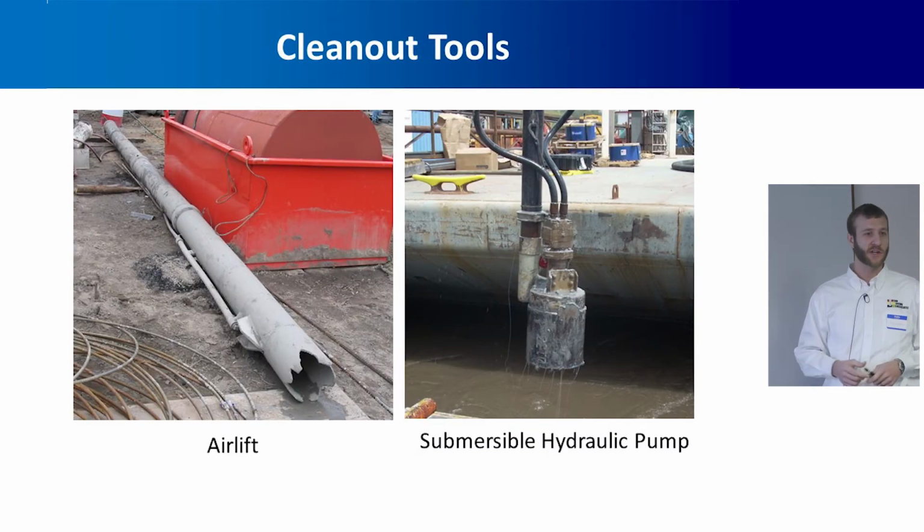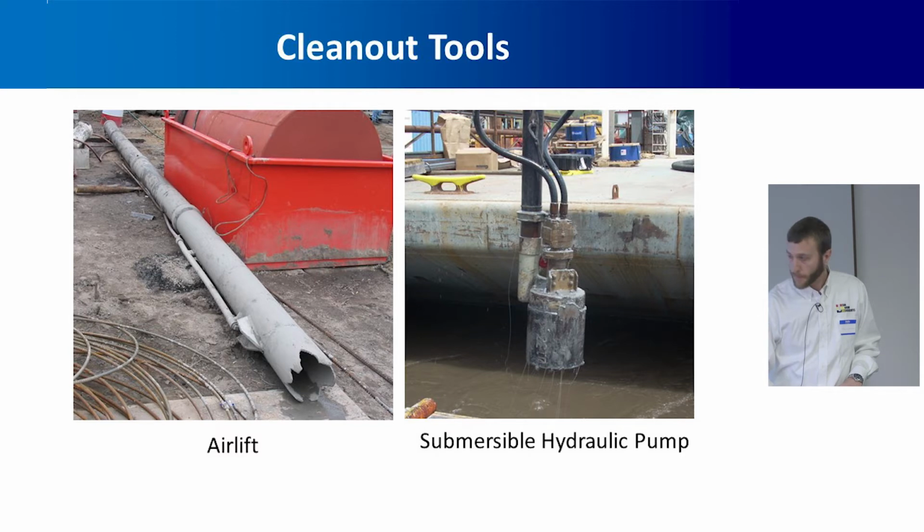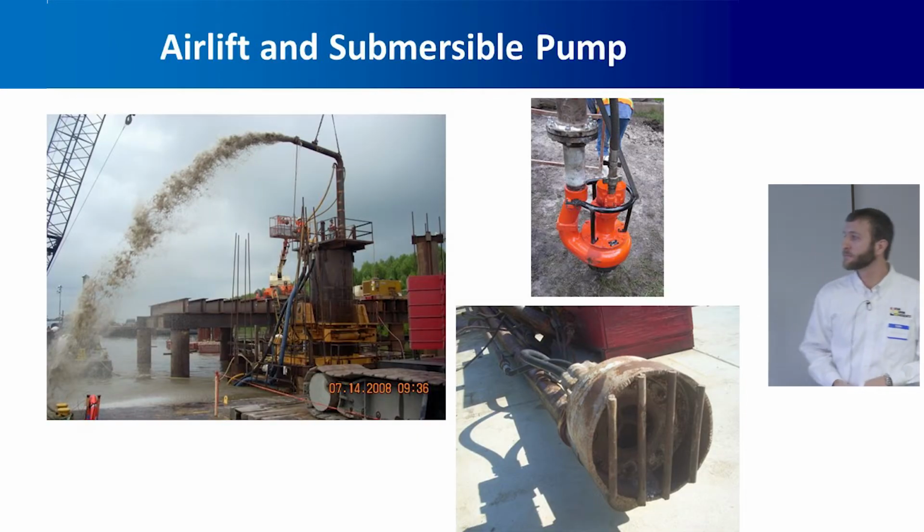To clean the loose material off the base of the shaft, and also to exchange the drilling fluid and get it clean before we place the concrete, we generally use either an airlift or some kind of a dredge pump. This is an airlift in action on a project down in Louisiana. And here's some other pictures of some hydraulic pumps.